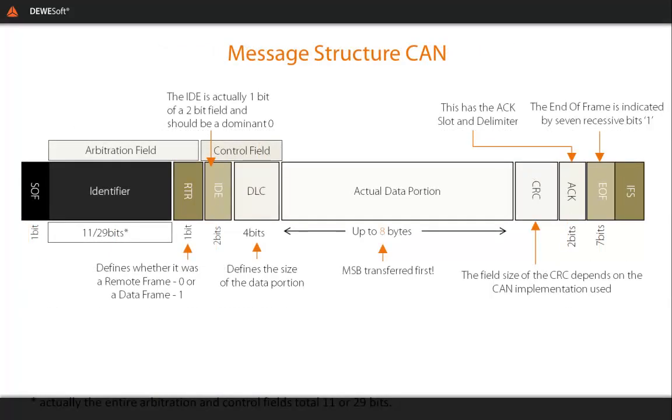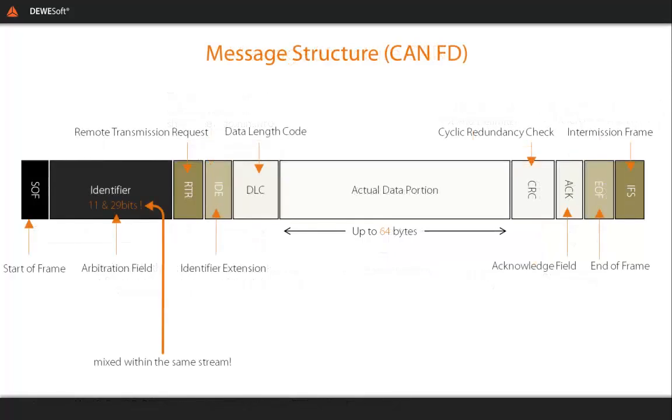This illustrates the structure for CAN standard and CAN extended. There is a specific number of bits allocated to each component of the frame. These vary based on the CRC requirement as well. A bigger identifier typically implies there will need to be a bigger CRC to check it. And a CRC is the cyclic redundancy check, for those who are not familiar with this. Now, as you can see, the payload with FD has been significantly increased, along, ironically, with the speed at which the frames can be made available. I guess newer technologies, faster, better, and all that.